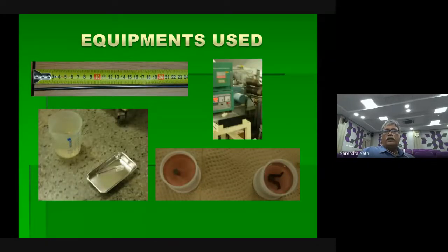And this is the equipment we used for further studies. I think everybody knows this. After sealing, after closing, then putting inside the furnace, after treatment we take it out. Now we have to break this. The quartz tube is going to break, and you will get a fine titanium nickel rod. This is the rod we used. These things are for metallurgical sample preparation for SEM to study microstructures.